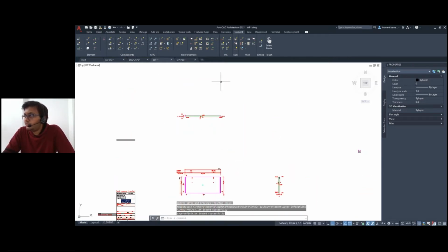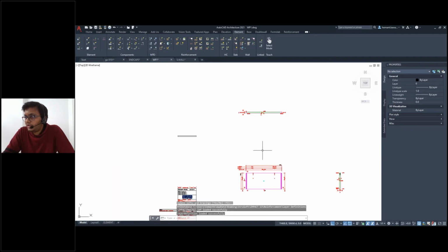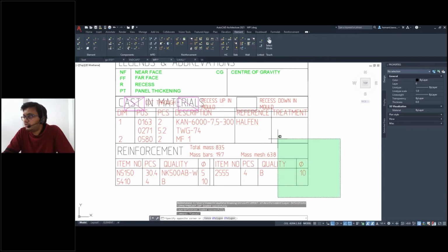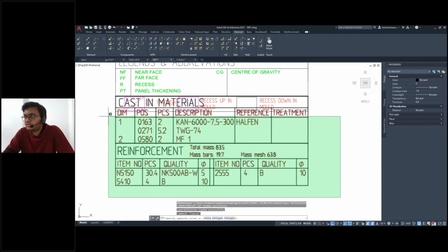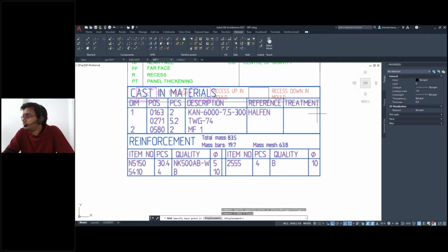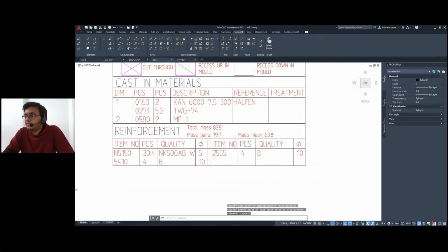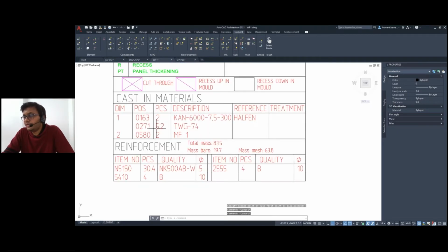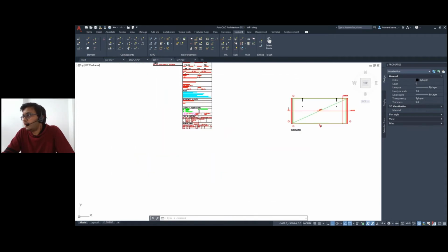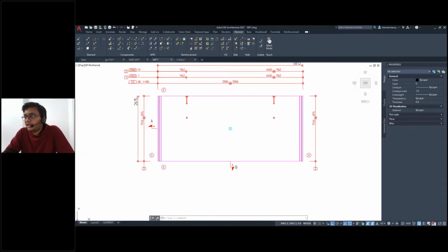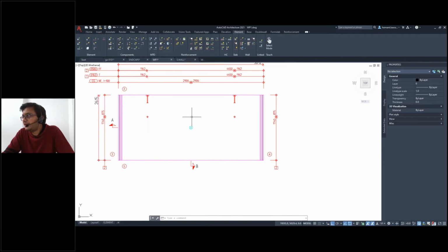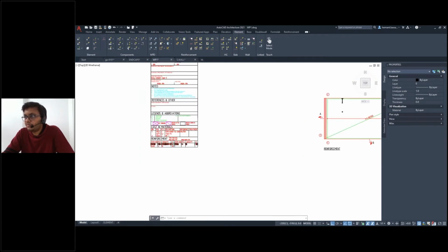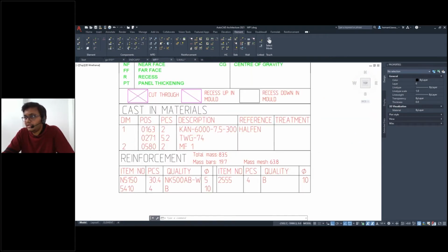Okay, now you can see we added the new geometry here, and if we go into the schedule, the linear footage that we added, okay, it overlapped just a little bit, I guess. The custom metal that we added is shown here, and the pieces, this 5.2, is in meters because we added it on the left and right side of the wall, and being 2600 height, twice that is 5200, so 5.2 meters of this linear shim will be required.